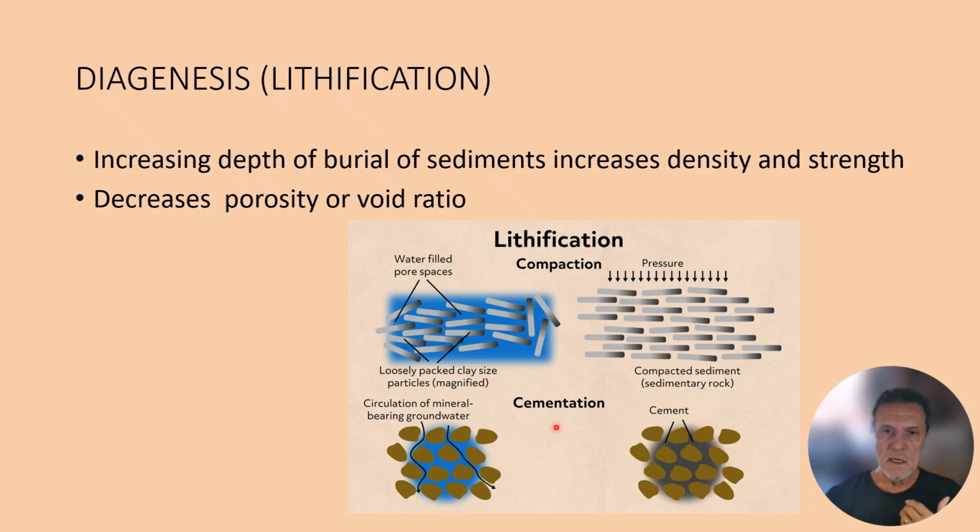And cementation takes place by virtue of water that carries chemicals and cementing material within it, like calcium carbonate or iron oxide. Circulation of mineral-bearing groundwater can promote the lithification process and cement particles of soil and rock together.